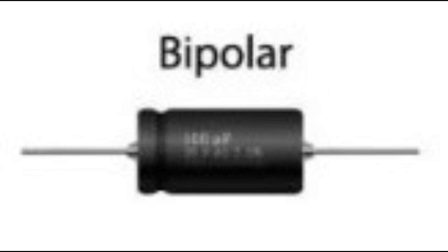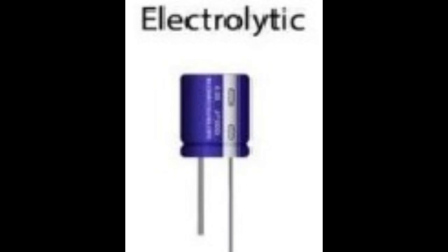Bipolar electrolytic capacitors, which may be operated with either polarity, are also made using special constructions with two anodes connected in series. A bipolar electrolytic capacitor can also be made by connecting two normal electrolytic capacitors in series, anode to anode or cathode to cathode. An electrolytic capacitor is a capacitor that uses an oxide film made of aluminum, tantalum, or other oxidizable metal as a dielectric.